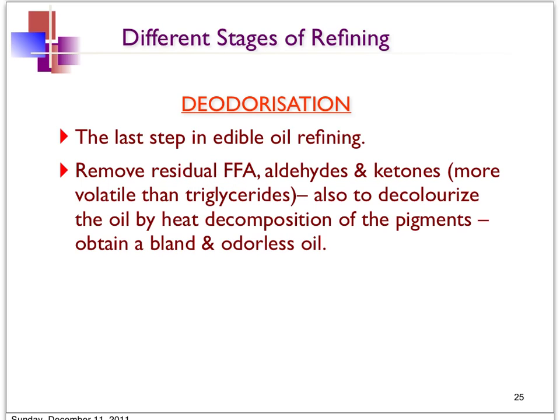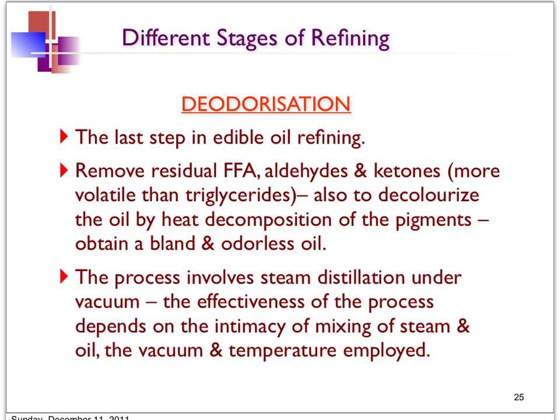The high temperature during the deodorization also would decolorize the oil because it will decompose the pigments in the oil. So the final deodorized oil actually will be bland and odorless. The process of deodorization is basically a steam distillation done under vacuum. So it is very important during this process to get a very intimate mixing of the steam and the oil, as well as the vacuum and the temperature.